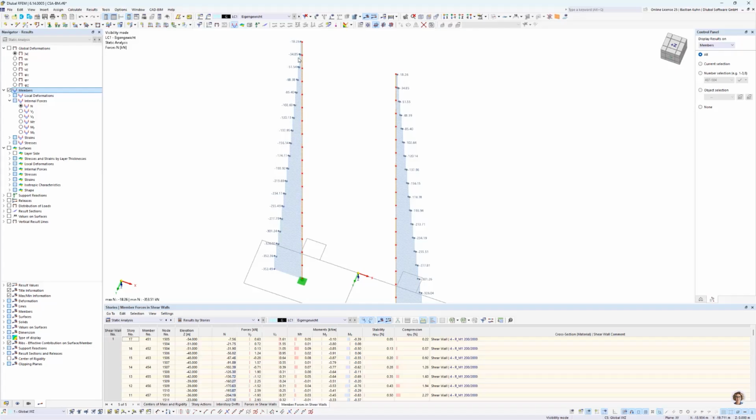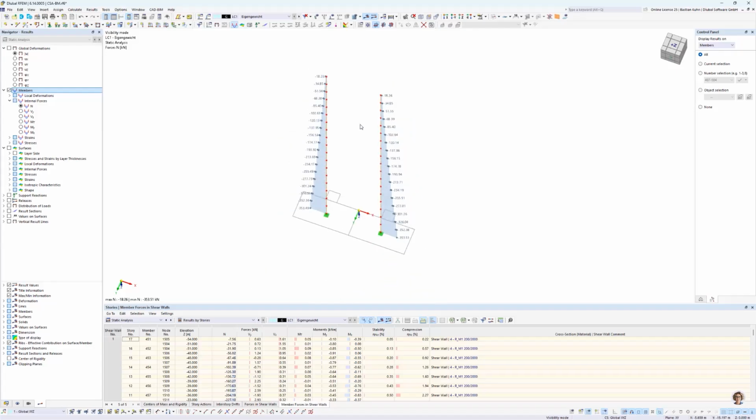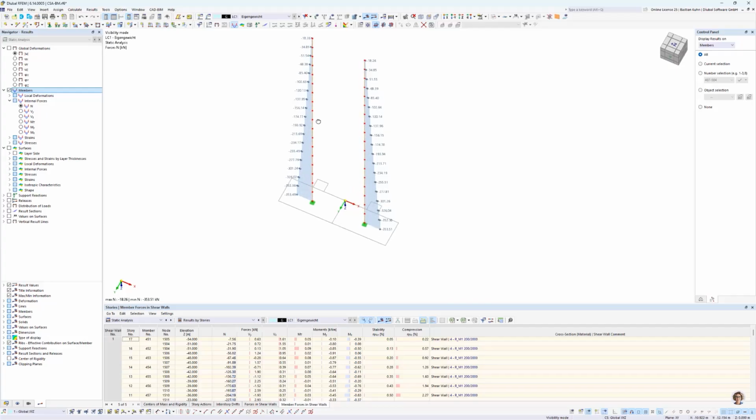And of course, in each story more normal force is coming, so that looks quite all right. But one will say I have quite a high loading of 3.4 kilonewton per square meter. And I don't want to recalculate that now in detail, but I also have a very high self-weight, or a mass in the center of 34 tons. So 18 for the center column probably is too low in here.